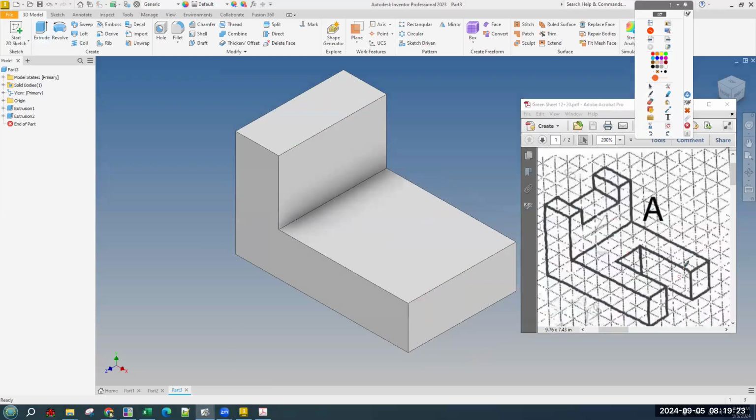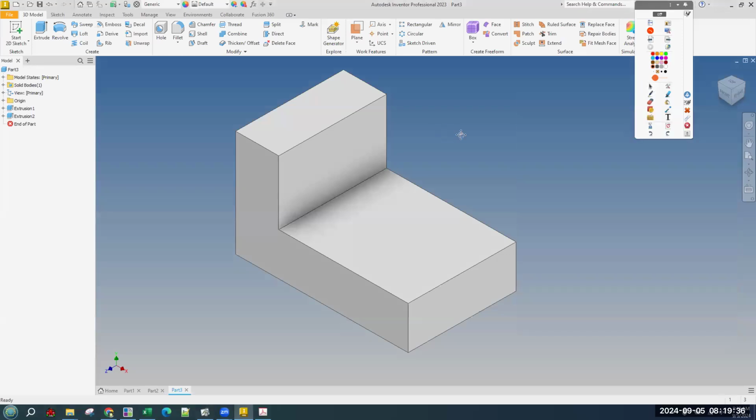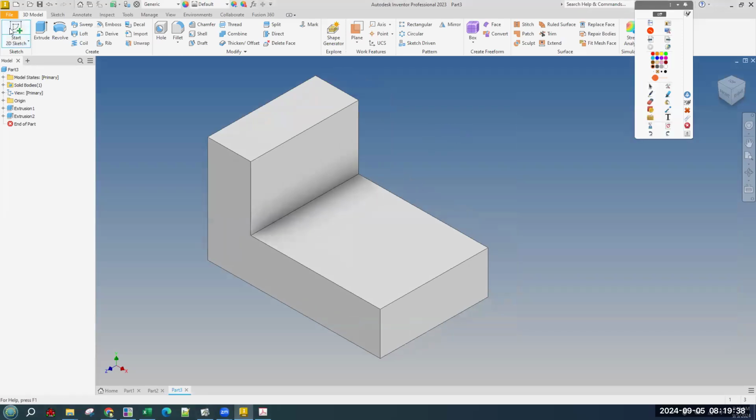We have 2 cutouts to make. The next one we're going to do is this shape right here. So we're going to put a sketch on this surface and then draw this rectangle, and we're going to do the same thing again of dimensioning the remainder. Like how far, instead of dimensioning the size of the rectangle, we're dimensioning how far the lines of the rectangle are from the side of the shape.